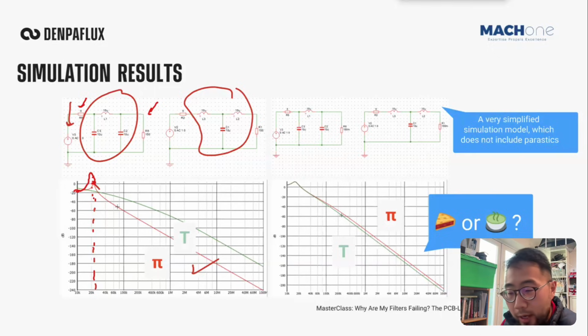And sometimes when you have two inductors next to each other, especially if you work for volume manufacturers making a filter, often you don't really select the shielded inductor, right? Shielded inductors are pretty good. They are widely used for switch mode power supply design, okay? And if you don't use them there, then you are inviting a big problem. But for a filter inductor, sometimes you don't really need a shielded inductor. Of course, you can use one, but that just adds some cost.